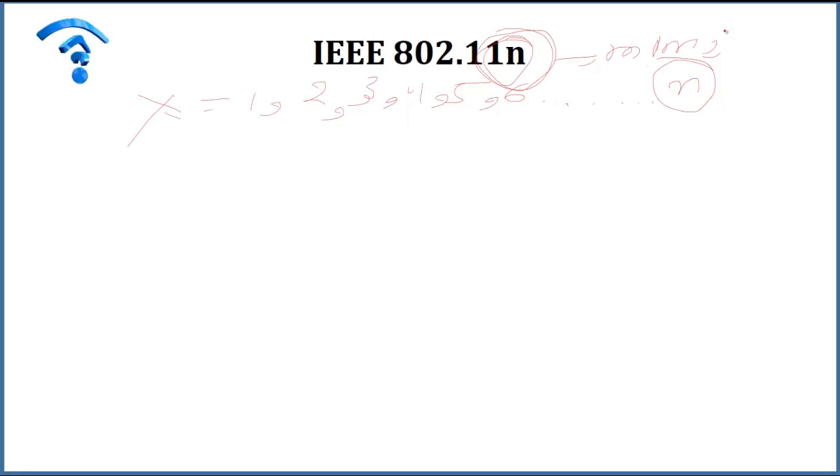Okay, so 802.11n employs an evolutionary philosophy, reusing existing technology where practical while introducing new technology. It provides effective performance improvement to meet the need of legacy technologies, such as reuse of OFDM, the forward error correction coding, interleaving, and quadrature amplitude modulation. These mappings have been maintained to keep costs down and ease backward compatibility.